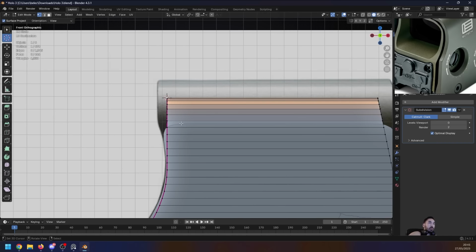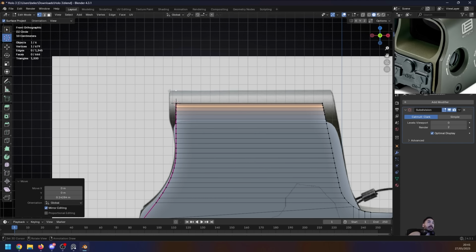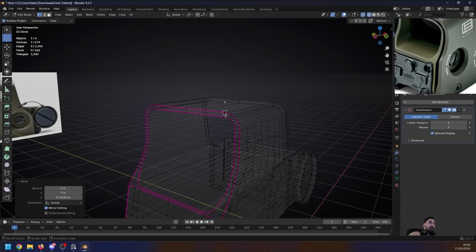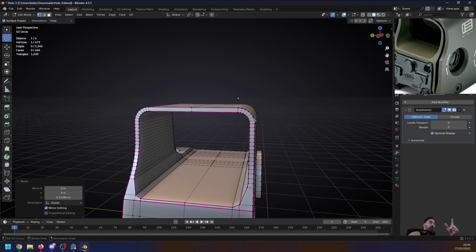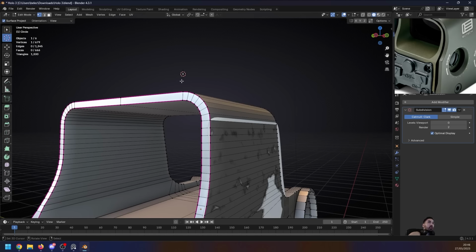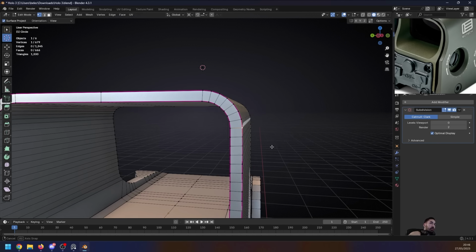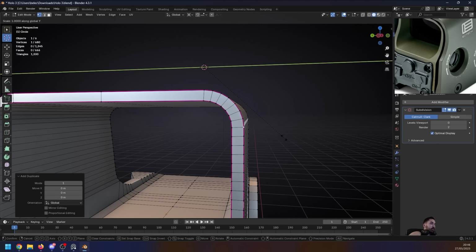We're going to go to side view, we're going to duplicate that vertex and place it up here on top of this edge over here, and this is the top according to the reference image, and we can use this to figure out how far this other surface on the side is supposed to be as well. So now we're going to place the 3D cursor onto this vertex. We're going to set the pivot point to 3D cursor, then we're going to select this outer vertex at the bottom of this bevel here. Shift D, right click, scale that to 0 on the y-axis.